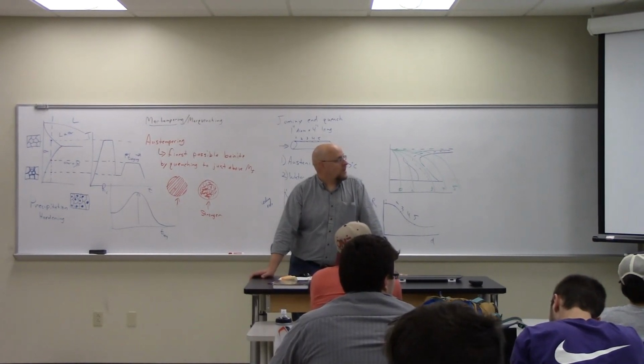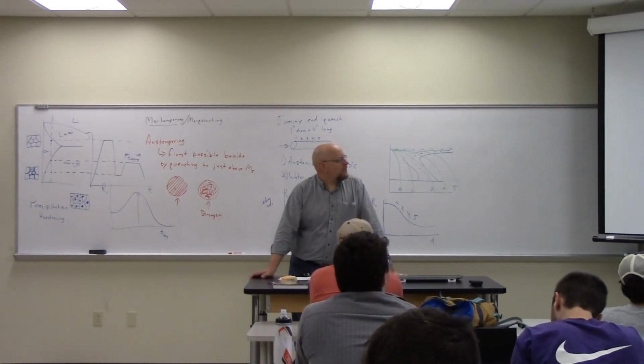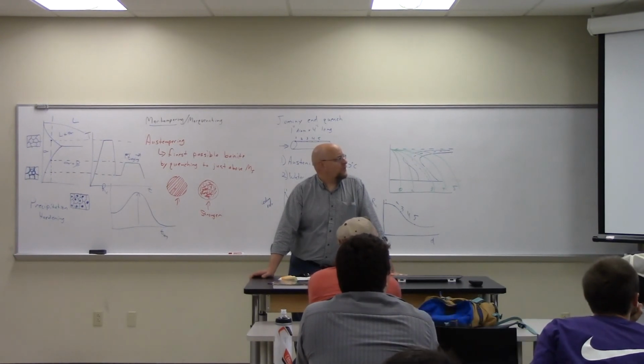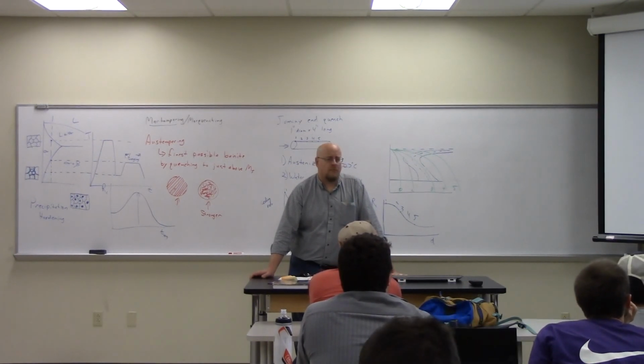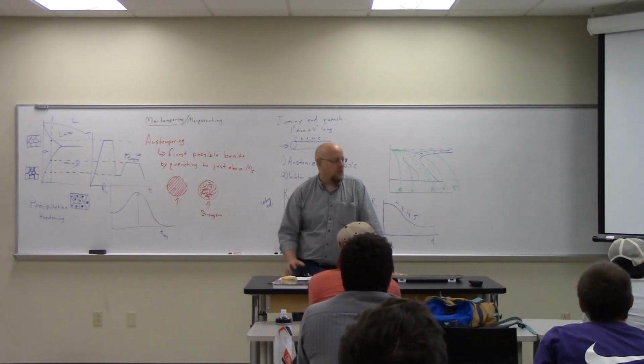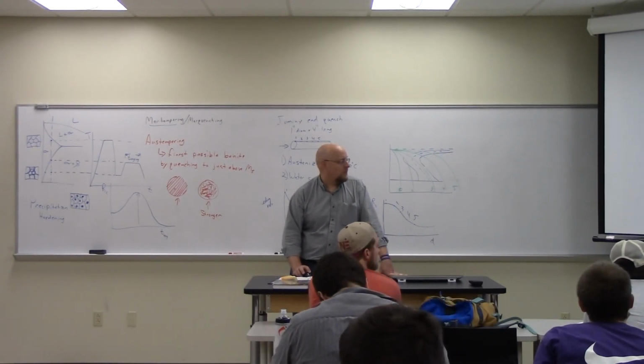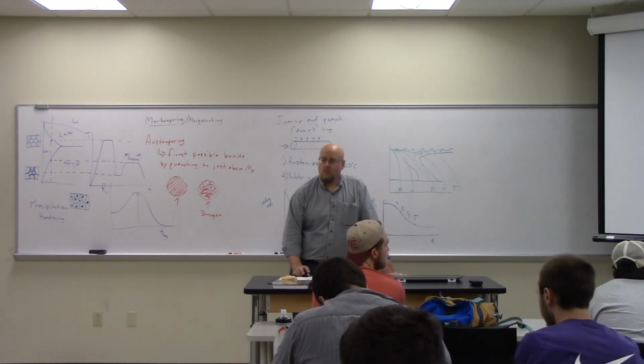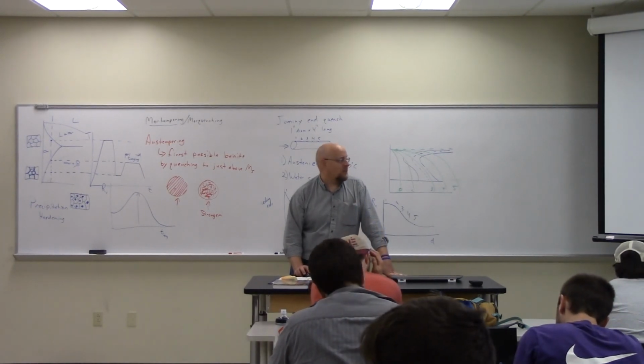So what is the phase transformation? What is the first phase to be observed? Martensite. The first phase to be observed then would be martensite. Because we miss the knee, we don't get any of that stuff, we only get martensite.